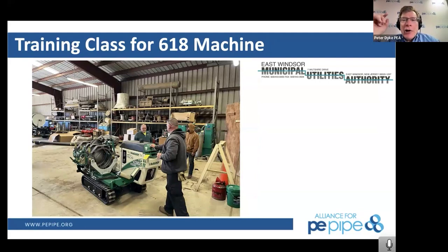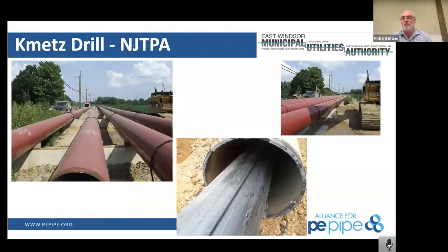So you haven't had any third-party damage yet? None. And you haven't had any butt fusion failures or any electrofusion problems? None. And we've been doing this for 10 years at a steady pace. Prior to that, we used it all for directional drilling. And when you're going underneath a roadway, if you feel that pipe is secure and safe enough to go 35 feet underneath the New Jersey Turnpike or underneath any stream bed, then why don't you put it in your distribution system?